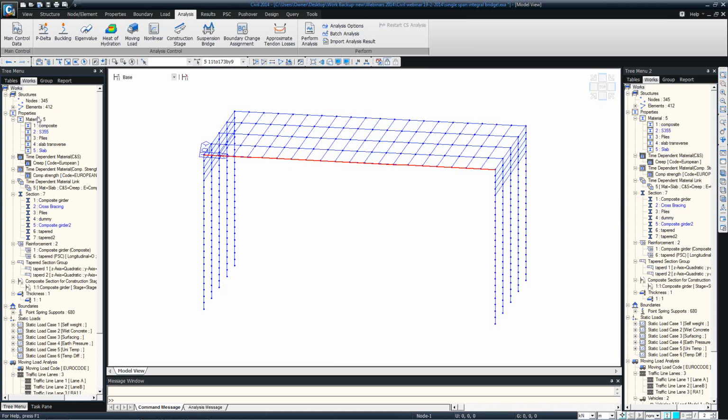We have another question related to the live loads. The question is: does it matter which reference beam we use as our starting basis for defining our lanes? It does not matter as long as you have defined the cross beam type of distribution. You can use some other lane and define some different eccentricity to match the correct position of the lanes. So as long as you have defined the transverse information that you want to apply the loads via the cross beams, it gives you the same results for any reference beam.